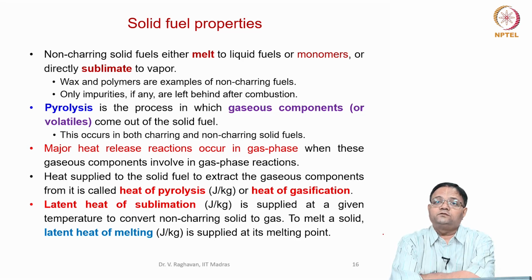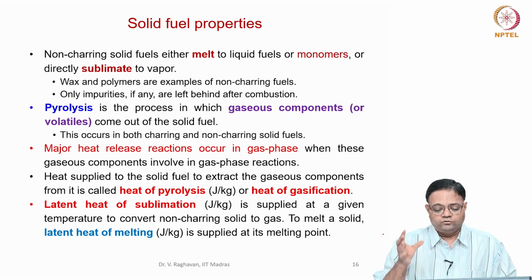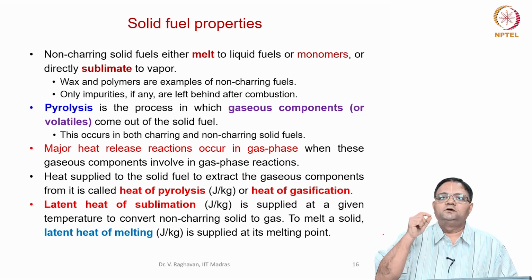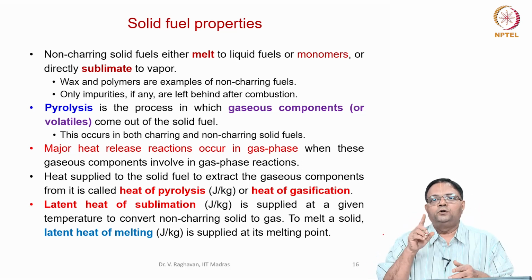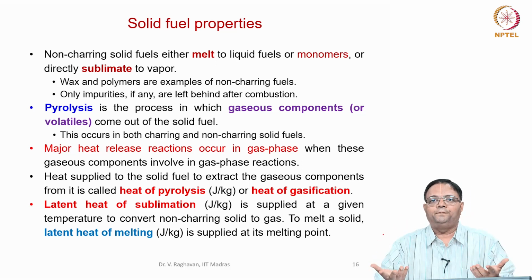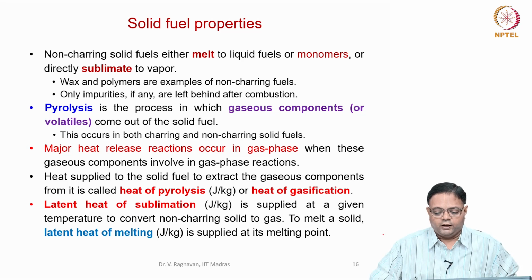So pyrolysis is the process of extracting the gaseous components from the solid fuels. It may be charring or non-charring. So how much temperature the solid fuel should reach, and how much heat I have to supply to the solid fuel in order to extract the gaseous fuel from them? That process is called the pyrolysis process.